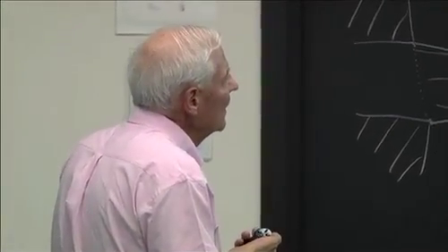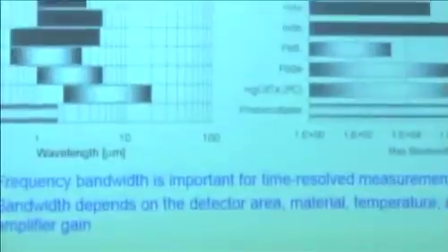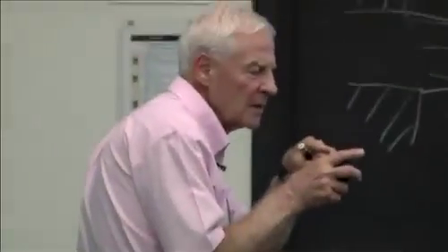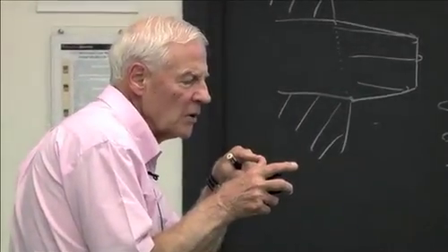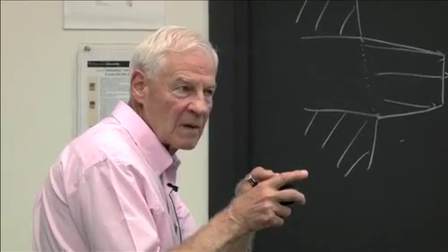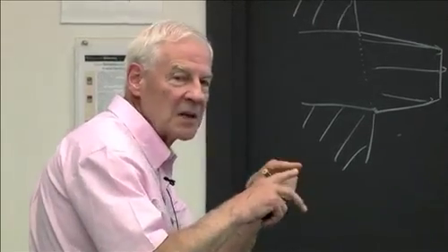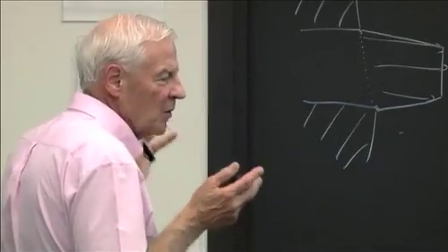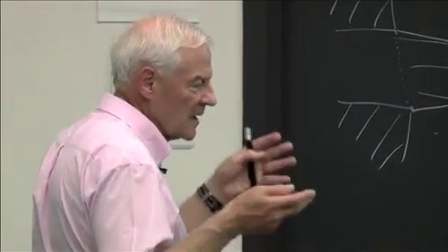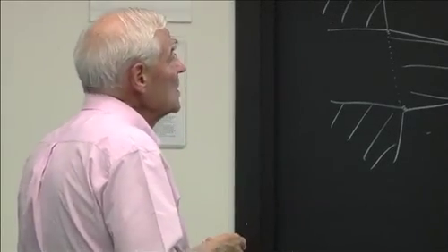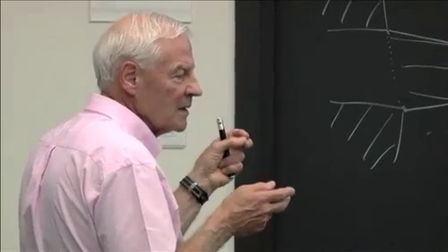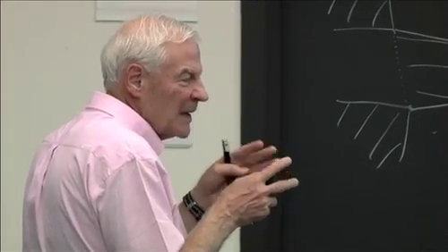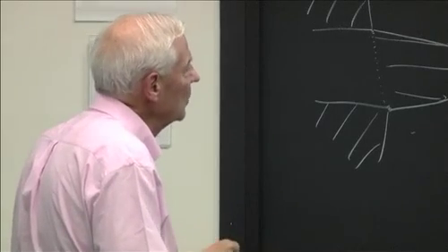Simple model is, a photon comes in and it has a certain probability of being converted to an electron. That's called the quantum efficiency. Might be 10%, might be 90%. Let's just say it's 10%. You've got to send in 10 photons to get one electron. The electron then flows in the circuit and you measure the voltage. So for the photovoltaic, a real simple model, photons go to electrons with an efficiency of, say for indium antimonide, up to maybe 50, 60%. They're quantum devices: quanta give you individual electrons. That's in contrast with a detector based upon heating, like a thermocouple or bolometer.